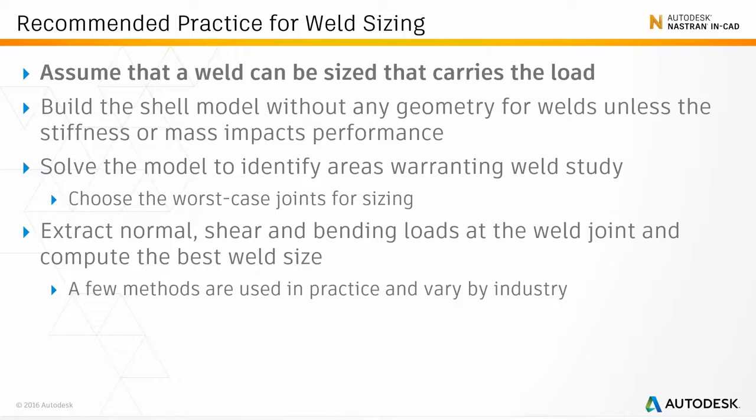So they're really the two key considerations for whether you include your weld beads in your analysis: one, whether it adds stiffness to your design, and two, whether the mass of your beads is going to affect the dynamic or inertial loads of your design.